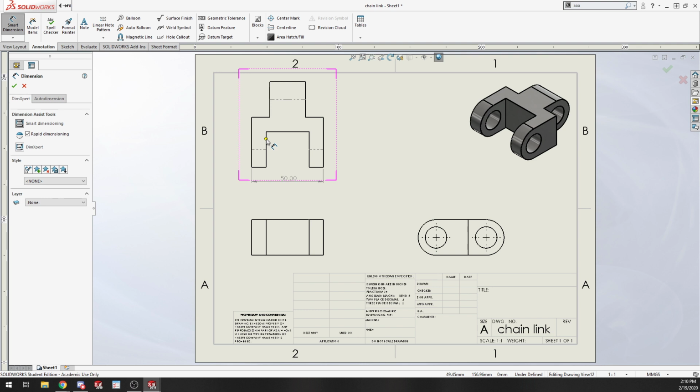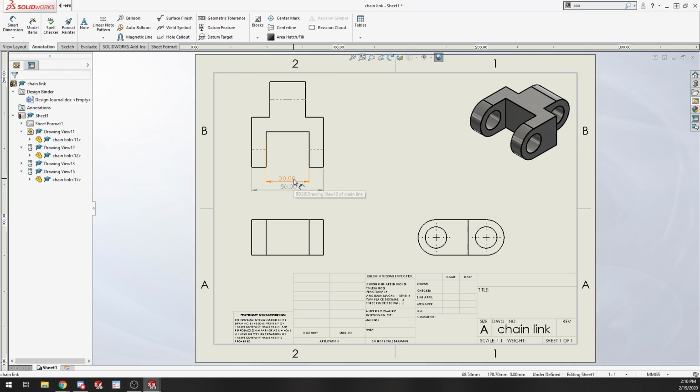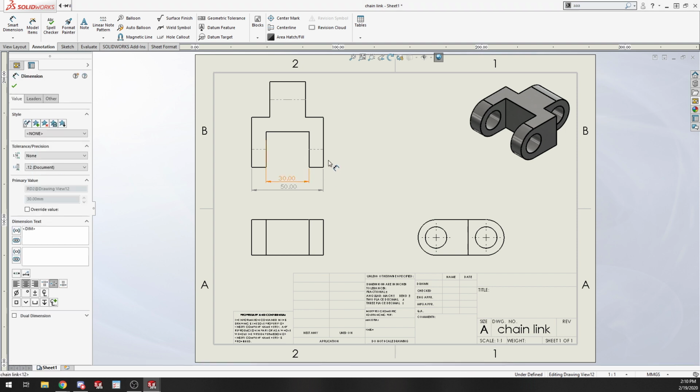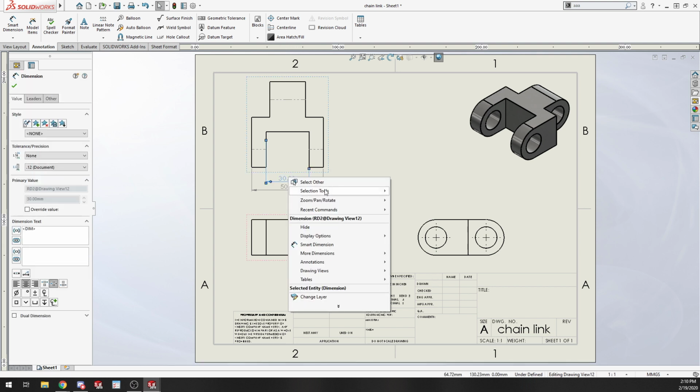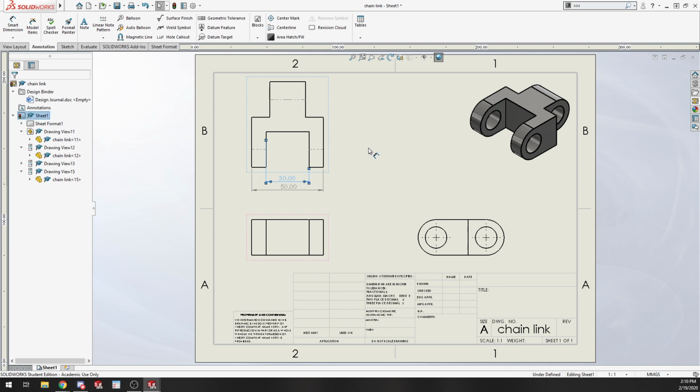Add that back in. Cool. I'm pretty sure you just click and drag over to take a peek. So basically, you can move these between different drawing views without redrawing them. Have to see, maybe it's shift. Yeah, there you go, it's shift, not control. So by clicking and holding shift, you can move between drawing views.